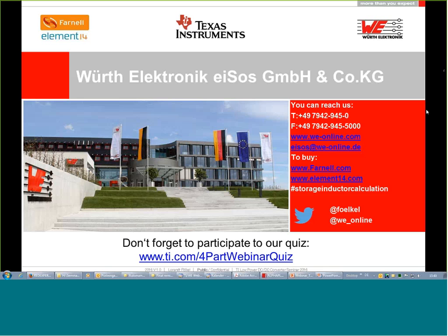Okay, another question. How would you measure the current in the inductor on the PCB? Do I need a shunt resistor? Well, when I measure the current in the inductor on the PCB, I desolder the inductor and solder in series with the inductor a piece of wire which is big enough that I can put my current probe for my oscilloscope. I have a very, very tiny current probe, and I put it on the leg of the inductor. In terms of EMI, it is not so good, but I can really measure the inductor current on the inductor itself using this copper wire.